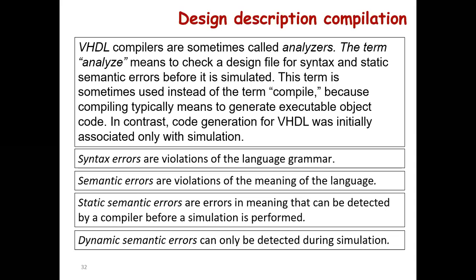VHDL compilers are sometimes called analyzers. The term analyze means to check a design file for syntax and static semantic errors before it is simulated. This term is sometimes used instead of the term compile, because compiling typically means to generate executable object code. In contrast, code generation for VHDL was initially associated only with simulation.